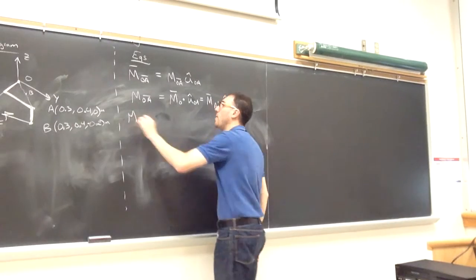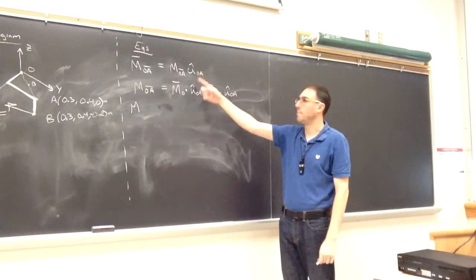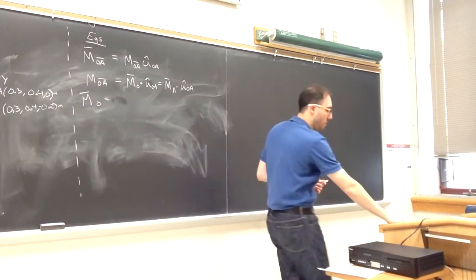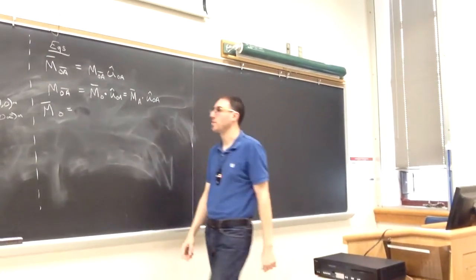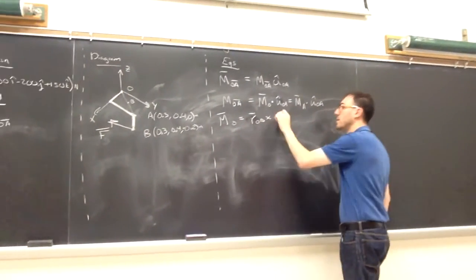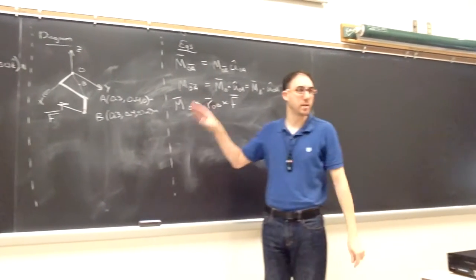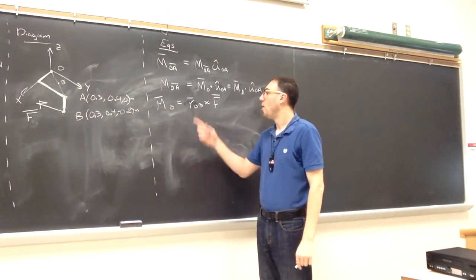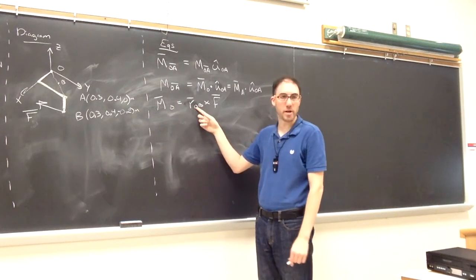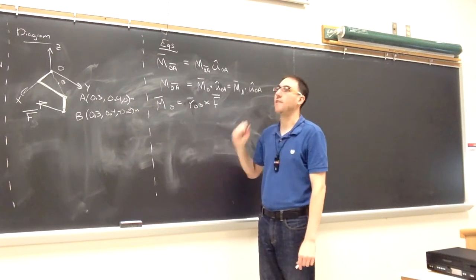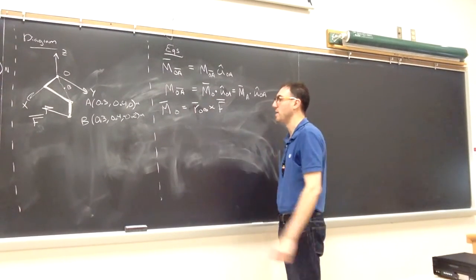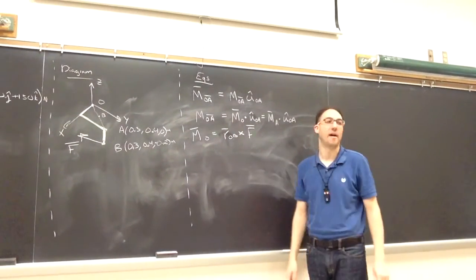So going one more step, we know if we find the unit vector up here, we know it down here. Right, we want to use the cross product. There's only one force in our problem. So what will the moment around point O be mathematically? Right, r cross F. This is what we looked at Wednesday. The moment around the point was the position vector that started at the point where we wanted to take the moment about. That's point O in this case. And force F is being applied at B. So this position vector goes from O towards B and then gets crossed with F.